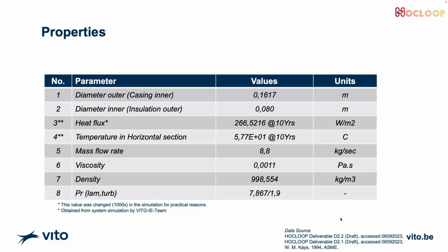That's my turn now. I was curious about the comparison between the results given by the correlations and the results of CFD. This is a case in which there is no streamwise pressure gradient, right? Because you basically have two concentric pipes, which results in a constant area channel in the streamwise direction. What if instead I induced a streamwise pressure gradient, I mean a diffusing channel or an accelerating channel? What would be the accuracy of those correlations in that case? Do you have an idea?